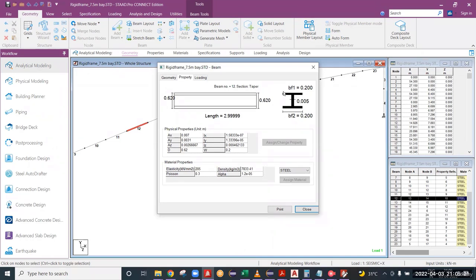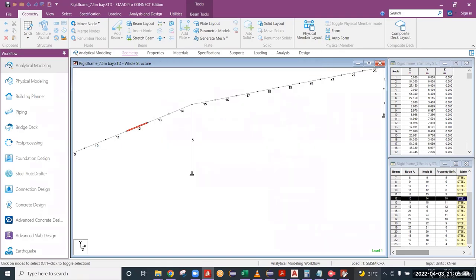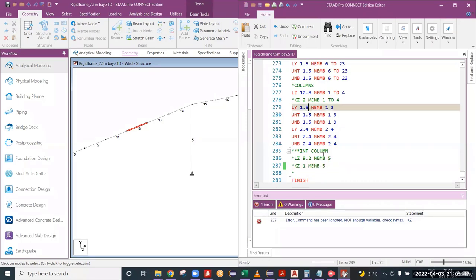I told you purlin will run over the rafter, right? If you see the cross section, purlin will run like this. The flange bracing support will come to the beam diagonally. In some instances they are skipping the flange bracing, using it alternately. That is a very good question. In that case, top length will be 1.5, right? Anyway, top of purlin will be connected directly to the rafter. The remaining two portions alternately, 1.5 into 2. Like this you have to give.